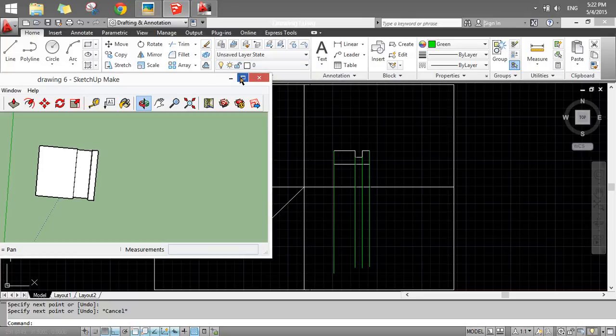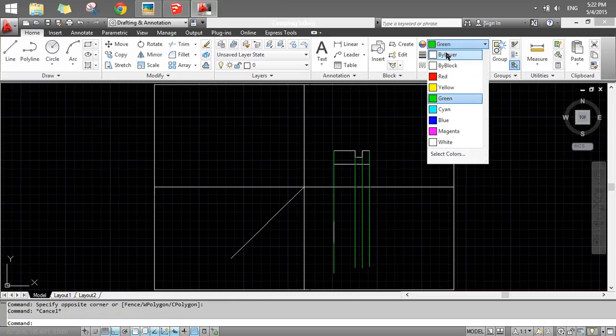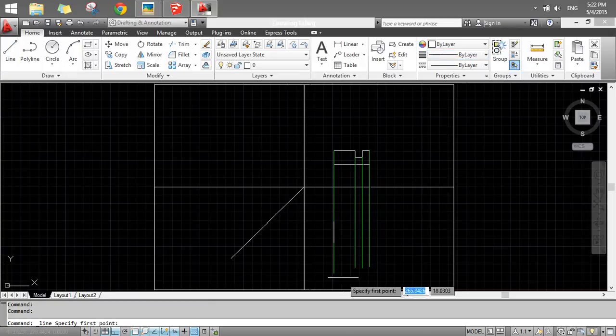So drawing that, since the length from this point to this point is already 50 units, you have to just draw a line, click here, drag it on the same line, backspace, 30 units, enter. Now you have drawn a line of 30. Click somewhere around here, the line will highlight, change the color to white, escape, otherwise also now change the color to white, click on line,